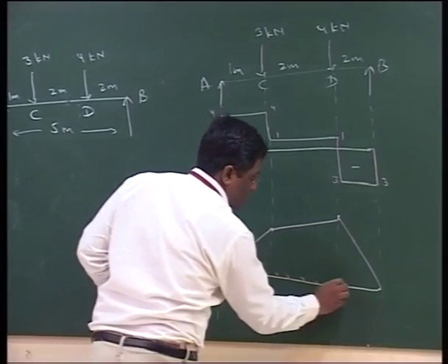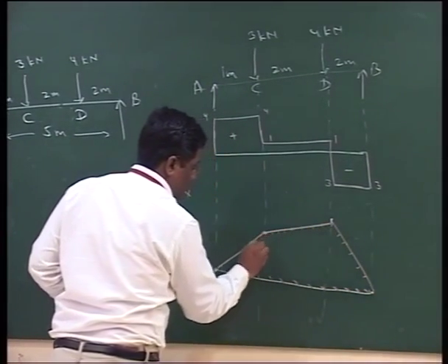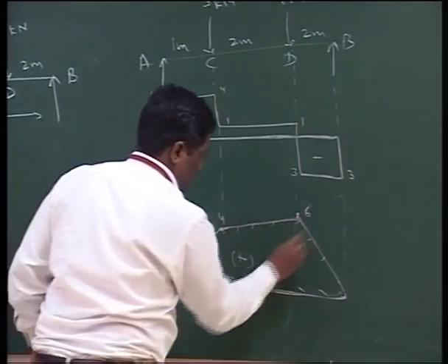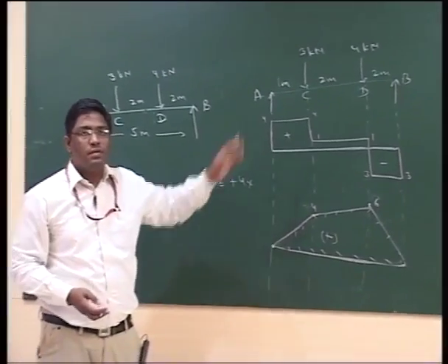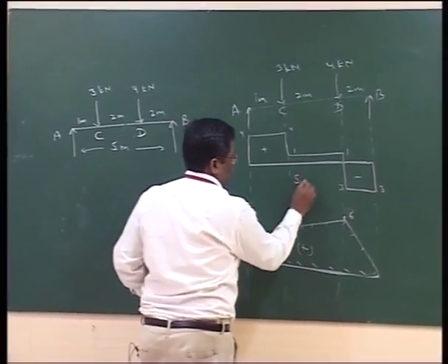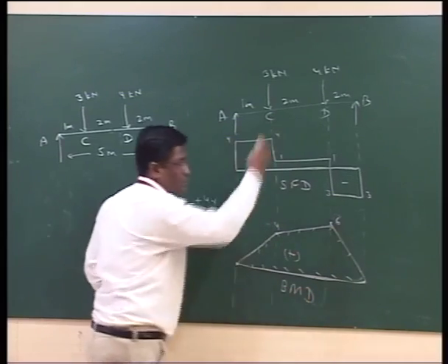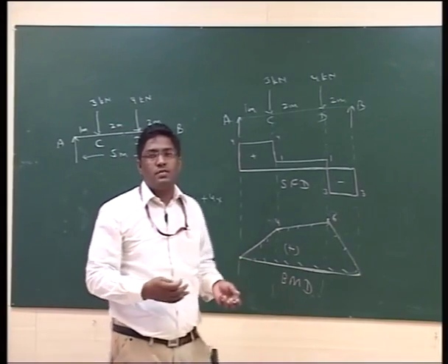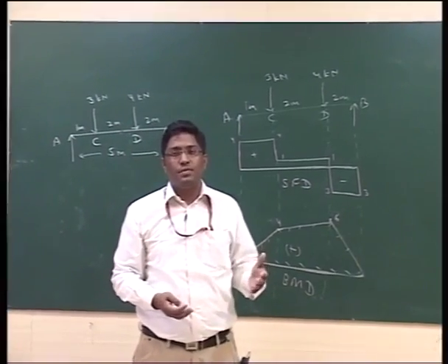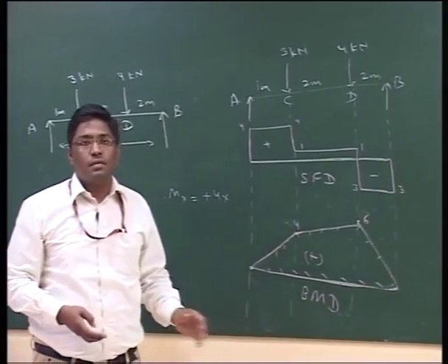So there is no portion of this bending moment diagram which is under the 0 line, and this will be plus. At any particular point of this beam, if we want to know any value of shear force or bending moment, quite easily we can produce the projection, and by this we can know it. So this is, students, the way to draw a shear force diagram and bending moment diagram, and to use such diagrams to analyze the beam. Thank you.